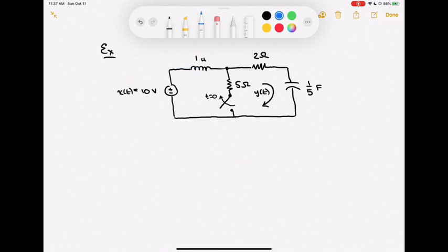And so I'm going to go ahead and just show that in here. I'm going to show that original state as being closed in there, something along those lines. And I've got a DC voltage source, 10 volts, right? That is going to be entering into this inductor that we've got in there. We know that that inductor is basically a short for a DC signal, at least once it's hit that steady state. So we should get something like 10 volts sitting out there at that node.